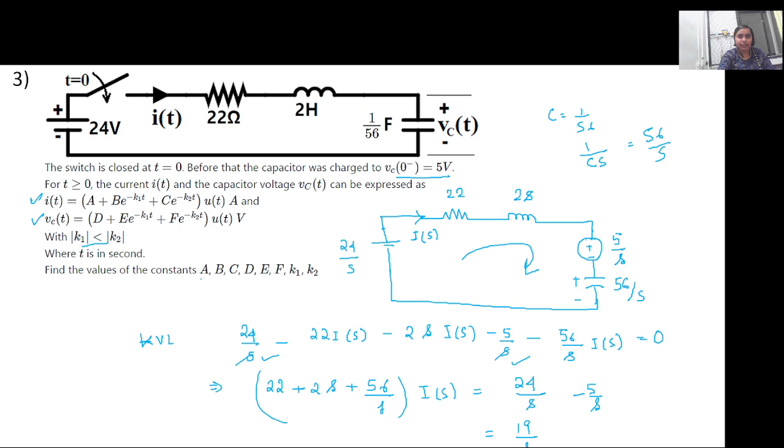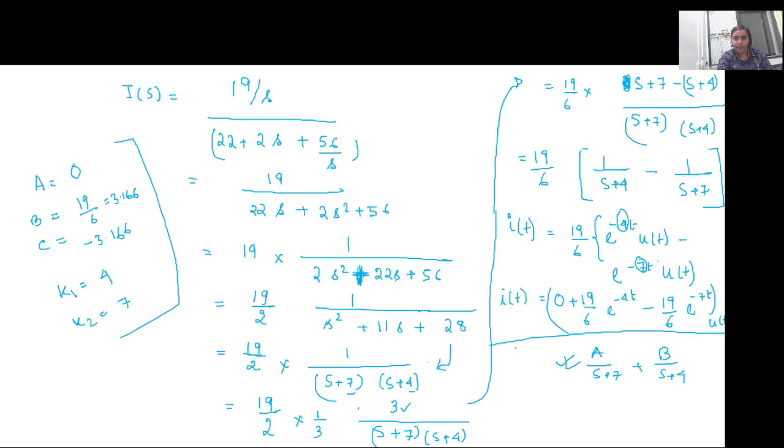Can you calculate V of C? So last time what we did was we calculated the equivalent resistance across this, and since V of C will be the same because this entire voltage will be divided between these elements and this. But right now since they are connected in series and there is a source voltage, we will calculate VC like the voltage that is coming across here, including what the initial condition was. So we will calculate it that way.